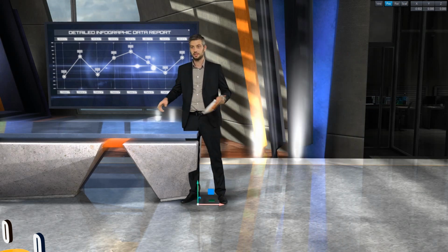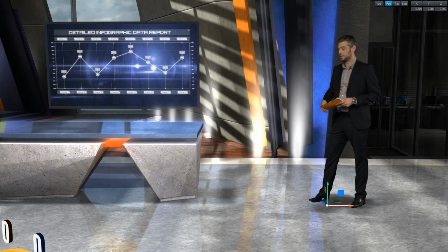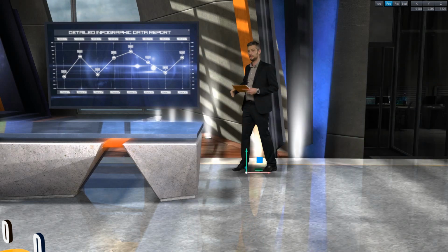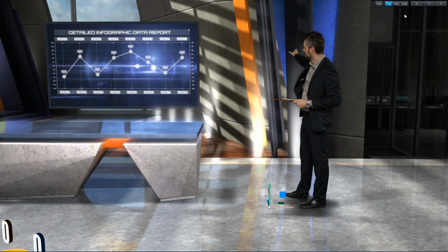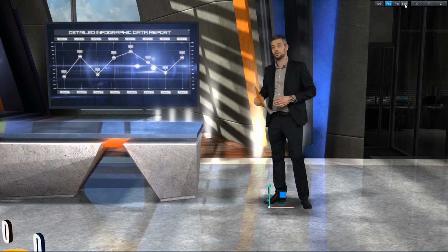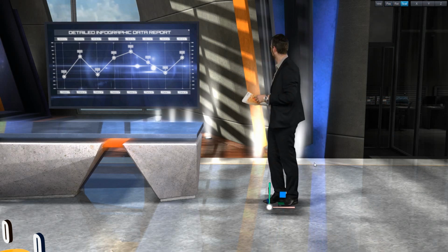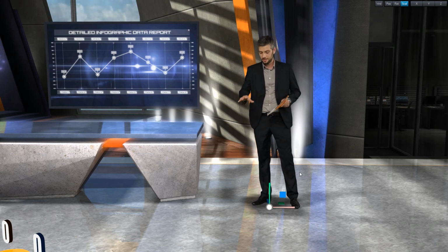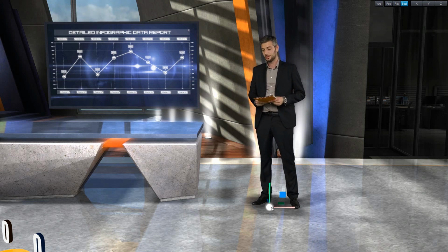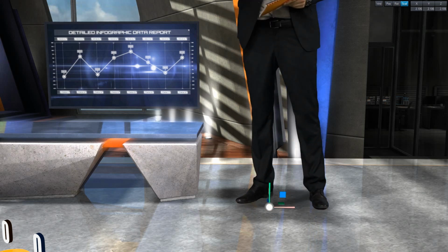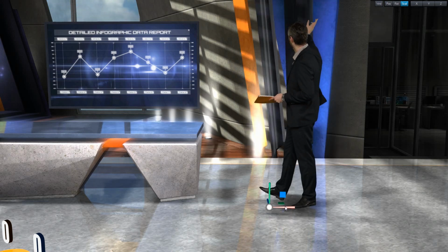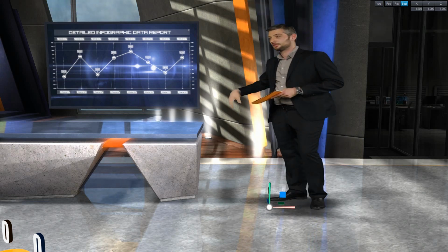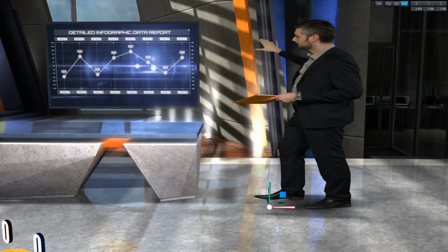I can now move the person in the 3D space freely, either with the help of the arrows or with the help of the small rectangles. By selecting the different buttons on the top, I can choose between different editing modes as well. If I, for instance, choose the scaling here, I can change the size of a person. A white sphere will appear that we can grip on with the mouse and move it in any direction. With this tool, we can easily adjust the size of the person. There is no reason to use the axis arrows here, since it will distort the image in the given direction.